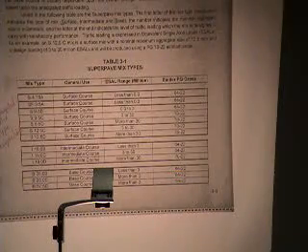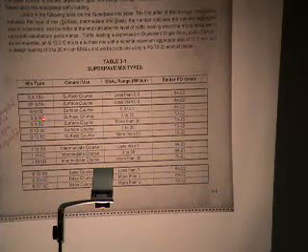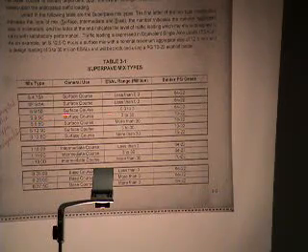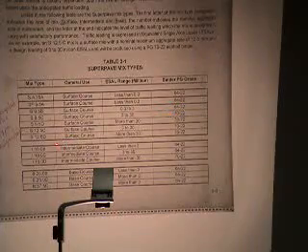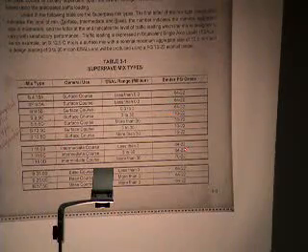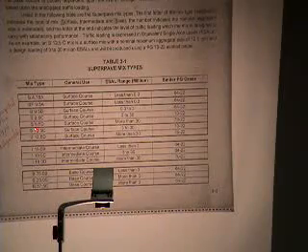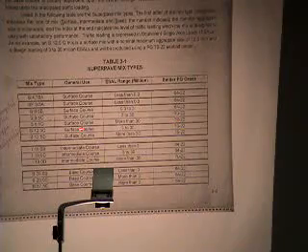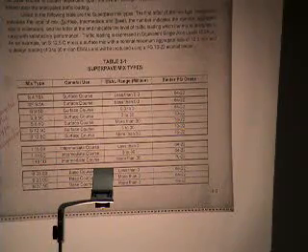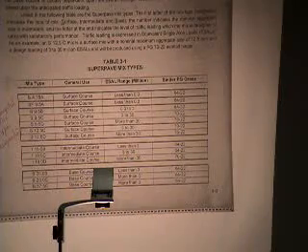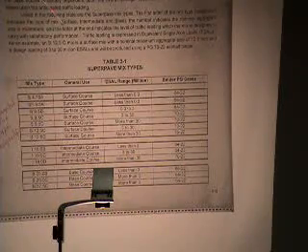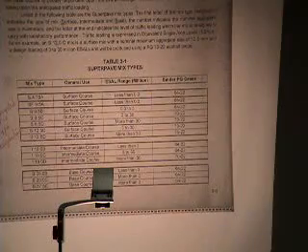And the question always comes up, well, if you're on your surface, on the C mix, you bumped up to a PG70, on the intermediate C mix, you stay with 64. And on the D level surface, you bumped up to a PG76, and on the D level intermediate, you only bumped up to a PG70. Now, why didn't we bump up the intermediate, just like the various traffic levels, just like we did the surface?